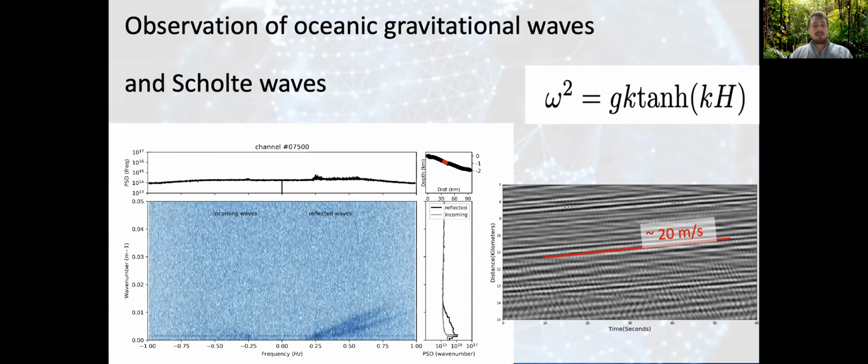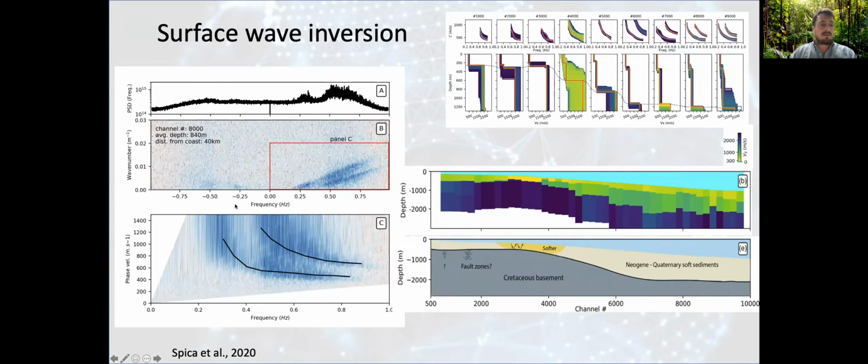So we can actually transform this wavenumber frequency diagram into a phase velocity frequency diagram. And here we can see that there are two clear modes of the phase velocity wave, Rayleigh waves in that case, because we have a linear cable. And we can extract the maximum amplitude of this signal. And so we have something that approximates the phase velocity of these Rayleigh waves. And we can repeat that measurement all over the array.